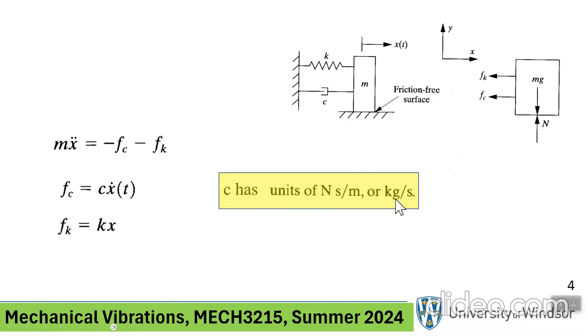Okay, just keep that in mind. And the spring force is simply kx. We are assuming that x is the amount of stretching from the equilibrium position. That's why this is the case. Now, if you plug these two into the top equation and take everything to the left-hand side, you get the mother of all equations where the damping term is present.